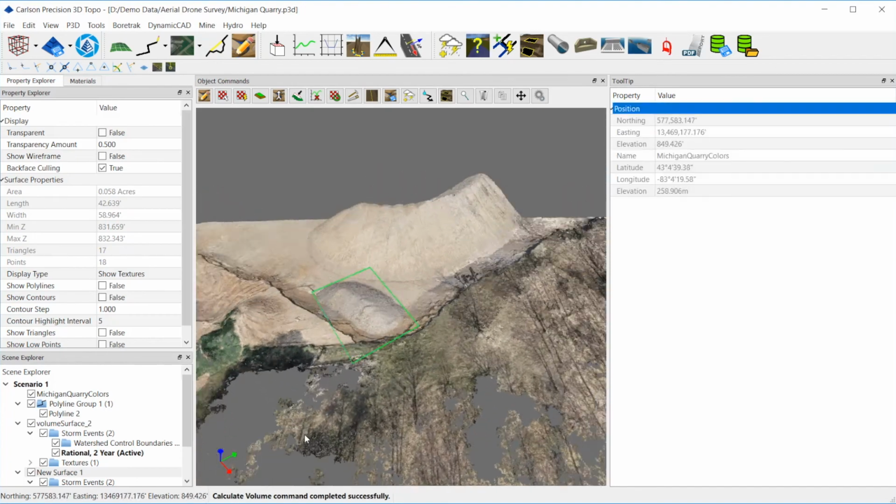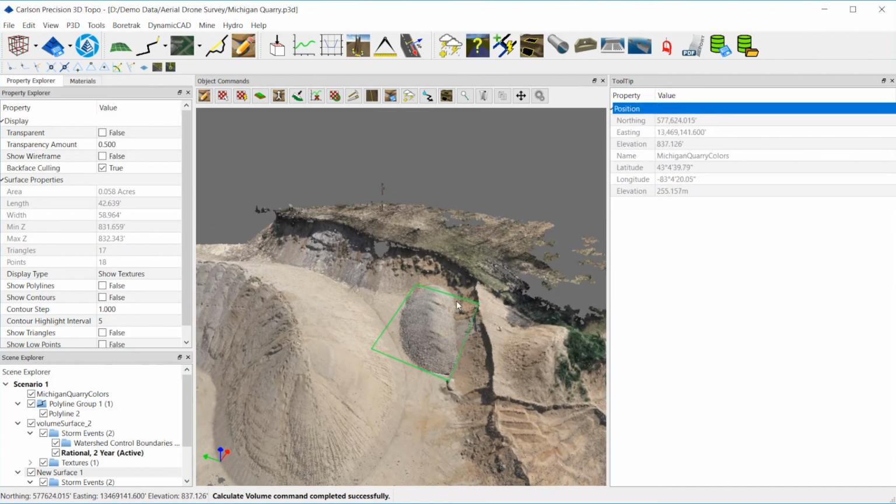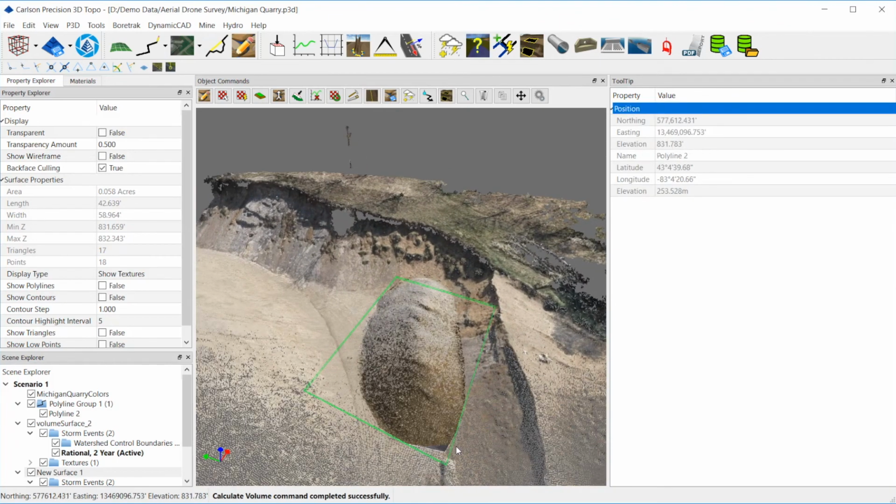So that's surface cleanup for volumes, creating volume reports, and then doing these tricky little volumes when you have a pile that encroaches on another pile or onto a concrete wall. And the retaining walls are even easier because you just take the elevations of the retaining walls at the corners, set your planar elevation to that, and so once you draw along the ground points, you just turn on the planar elevation snap, and from the top down, you just trace right along the inside edge of that wall, and you'll get a very accurate result for your volumes.